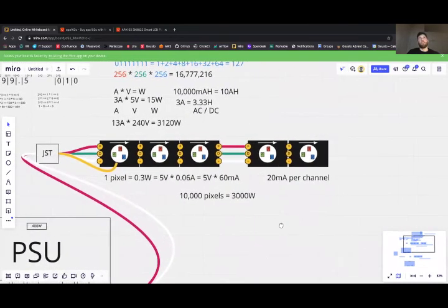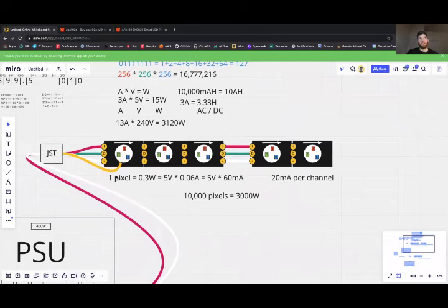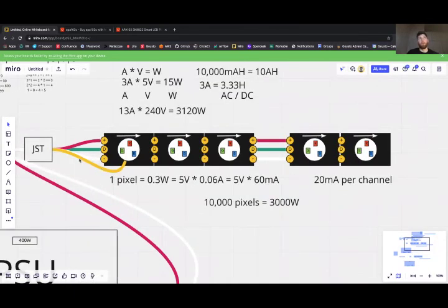And I won't go too deep into the details of what the purpose of this is, but ultimately it is a synchronization digital signal that enables chips with a clock pin to achieve higher refresh rates, higher frame rates. So you can actually display more data, more colors, more information per second on these LED chipsets.